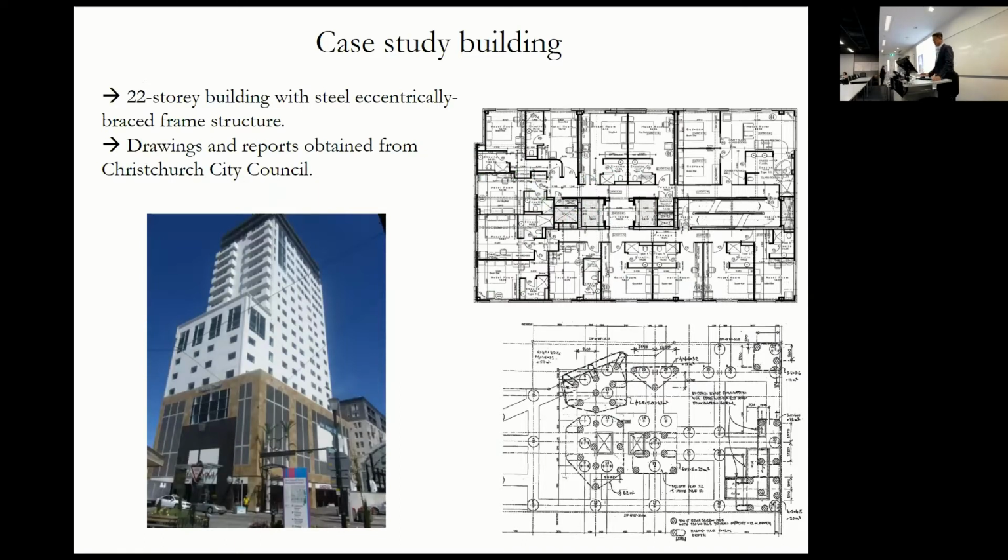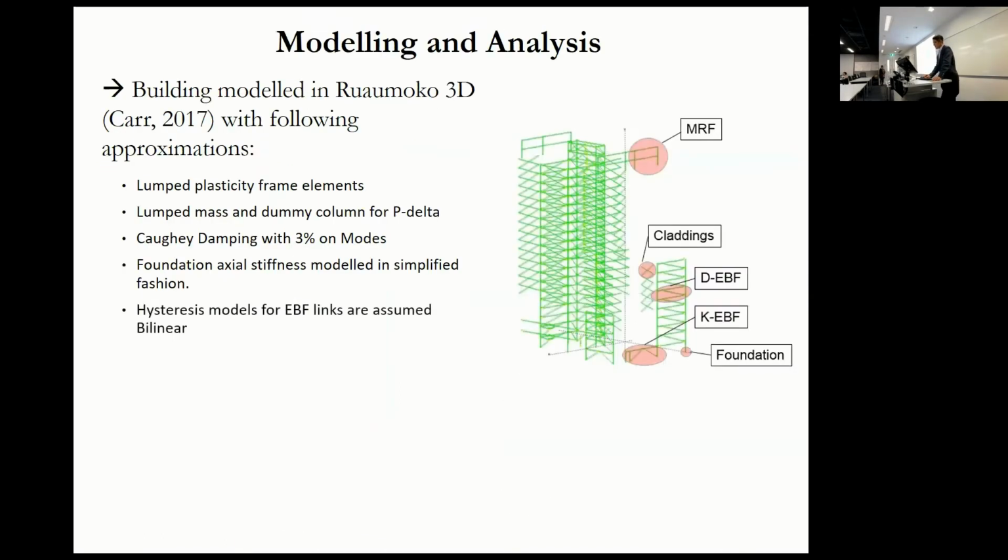So we made an estimate based on geotechnical information that we had in the geotech report. But we also did sensitivity analyses to our modelling assumptions. We tried varying, for example, we ran 2% and 5% damping and reran and looked at the results and tried to gauge whether our conclusions would have changed, and they wouldn't, in the sense that what we're going to talk about today, our conclusions wouldn't change.